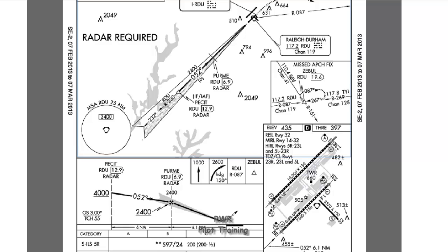All right, so according to ForeFlight, a chart there, it's 3,000 at Sand Hills. So the approach starts here at Peckett at 4. So as soon as we start talking to approach control, we might want to ask for direct Peckett, and then ask for the straight in.